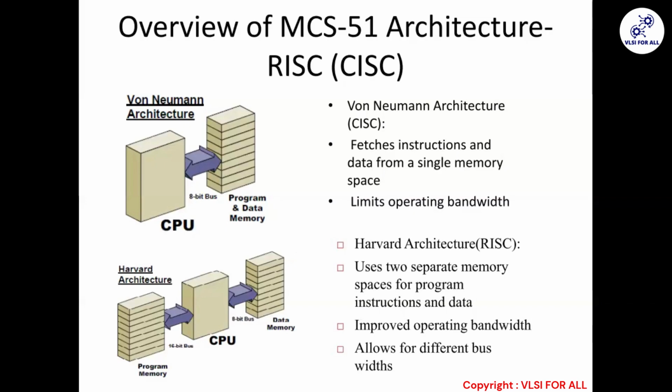And what that Harvard architecture is specifying, look at the second diagram. The data memory and program memory are separate. As we have seen in the previous diagram, ROM and RAM were separate. In a similar manner, data memory, that is RAM, and program memory, that is ROM, are separate. And what you can think of now? That the bandwidth dealing with the program memory and the bandwidth dealing with the data memory are separate, and thus we have the chance of keeping different bandwidths.